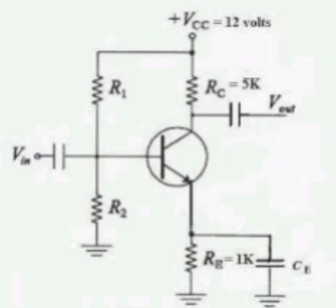Here the base of the transistor is connected to the ground, and the collector is connected through R1 to VCC. The base is shorted to the collector, and the emitter is grounded. One more transistor is connected, having only an emitter resistance R2, that's all. That is called the Widlar current circuit.